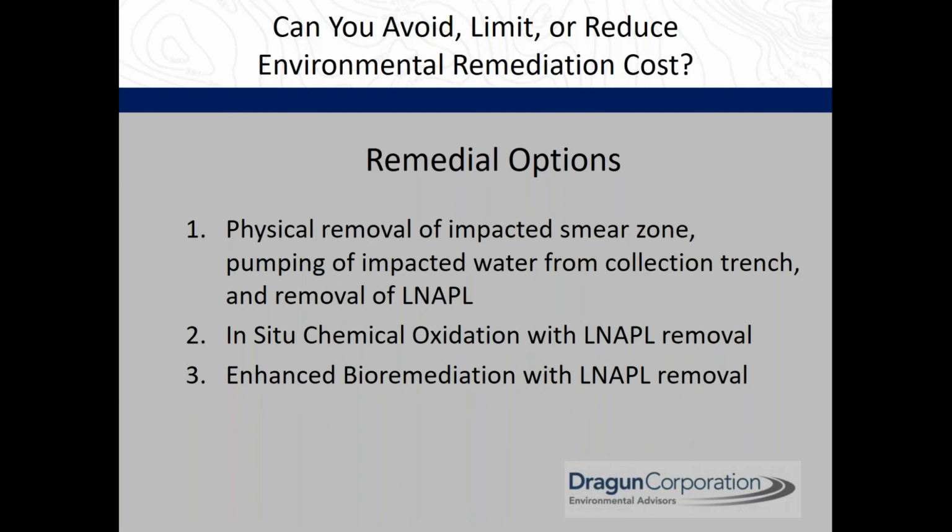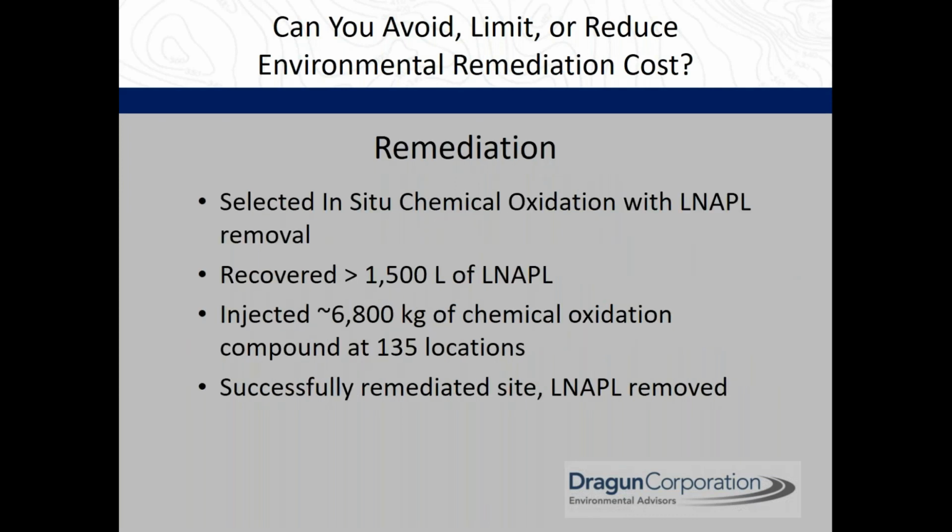The in-situ chemical oxidation option was reviewed and evaluated and scored high in the way we score our options, and was less intrusive, lower cost, will still meet our project goals, and we believed at the time when we assessed everything, it would meet all of our clients' objectives. We also looked at enhanced bioremediation. Costs were a little closer to the in-situ chemical oxidation, but we decided to go with the chemical oxidation because we felt that there was a higher level of confidence that we would achieve all these goals that we had outlined with our client. So we selected the chemical oxidation.